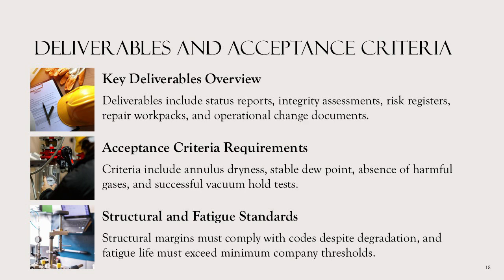Acceptance criteria require annulus dryness, stable dew point, absence of H2S, and successful vacuum hold. Structural margins must meet code requirements even with degraded sections, and fatigue life must exceed company minimum thresholds. These deliverables and criteria ensure transparency, compliance, and effective integrity management.